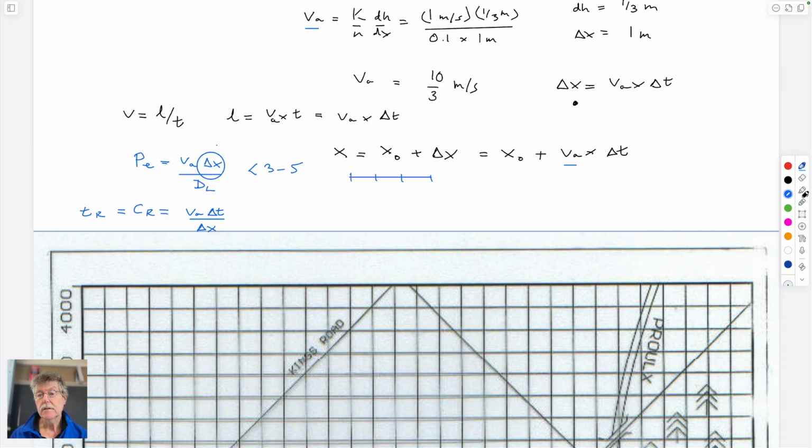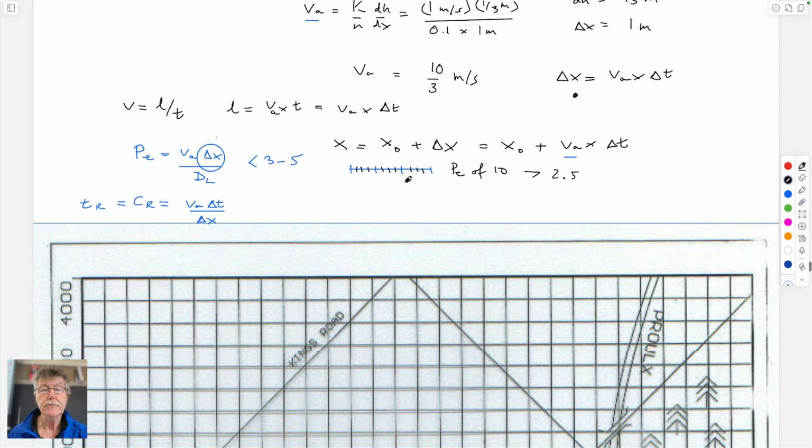this, looks like this. So this will take a Peclet number of 10, I don't know, and reduce it to a Peclet number of 2.5, because I had about 4 of these things in each division. So you can't control the velocity, you can't control dispersion, but you control it by making a really fine mesh, and then you potentially get a good solution.